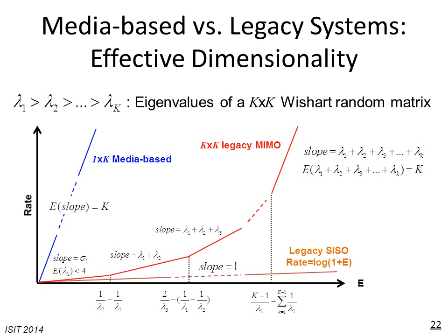Now let's look at the outcome of the fact that the channel matrix in a K by K MIMO is not orthogonal. As the channel is not orthogonal, in achieving the capacity, when the transmitter knows the channel, it is well established that we perform eigen beamforming, in the sense that we use the eigenvectors of the channel matrix as the basis, and we do water filling over the coordinates corresponding to the individual eigenvalues of the channel matrix.